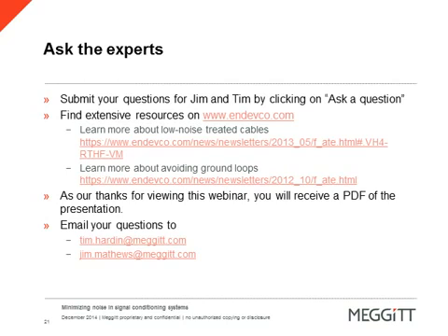For this, again, you want to have one point ground. Since there are different types of accelerometers, one being grounded, one being isolated, you could still use an isolator if you choose. If you use one that's grounded and you don't use the isolator, then, of course, you need to isolate the signal conditioner. Vice versa is also true.